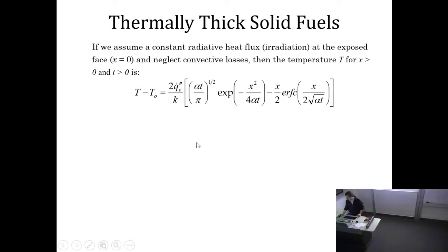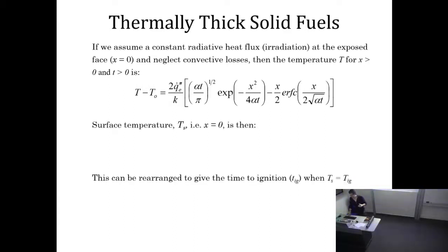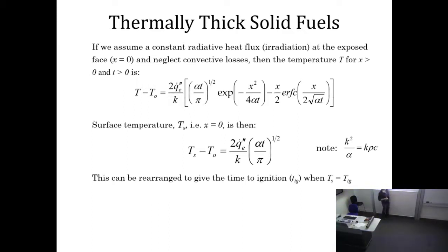If you're just interested, which is what happens very often, not in the temperature at any location but in the temperature of the surface, then the expression simplifies tremendously. At x equal to 0, that's the free surface. That's the first point that will ignite in most cases. Then the temperature of the surface with respect to the initial temperature grows linearly with the heat flux. It grows with the square root of time, which is quite interesting, and is proportional to the square root of thermal diffusivity divided by conductivity, which is K rho C.